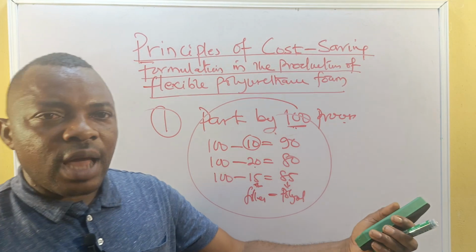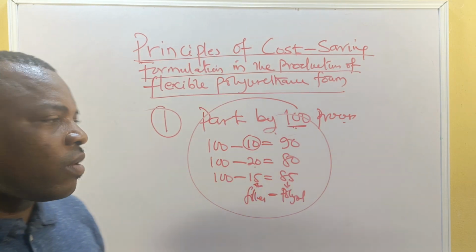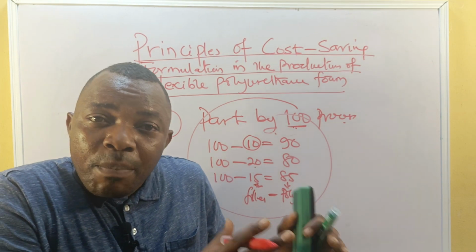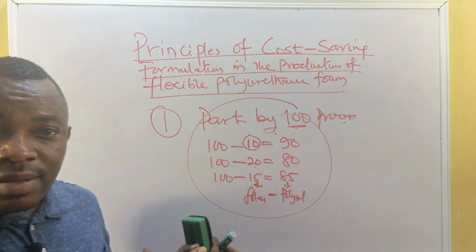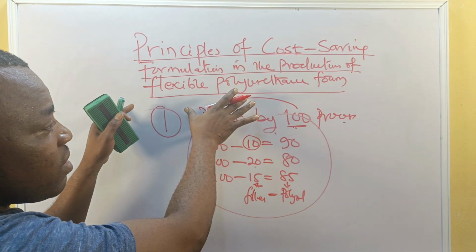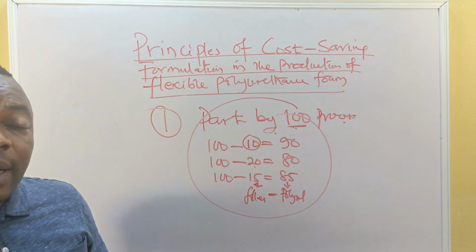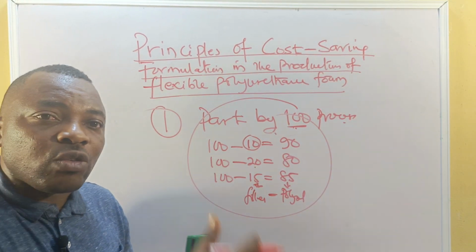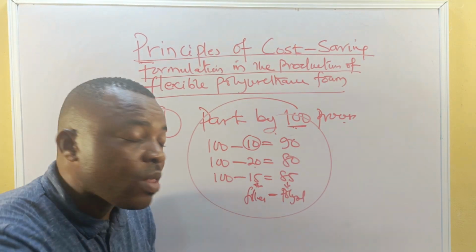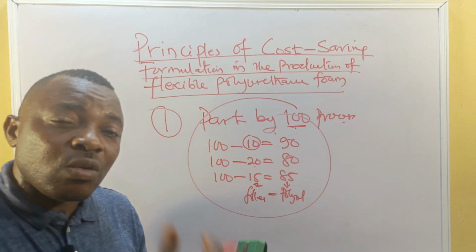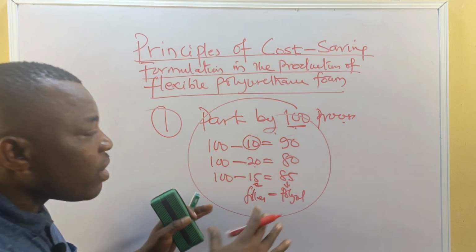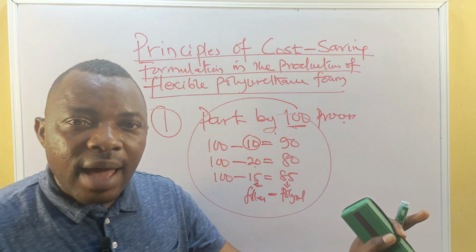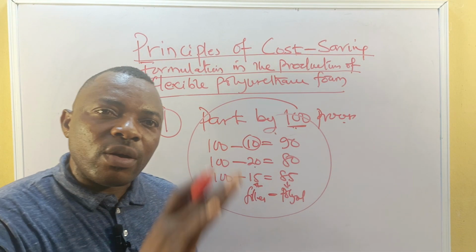Now, before you go into entire production, as a manufacturer that is using a continuous process, you must also put safety parameters or safety measures in place, okay, regarding your formulation techniques, in terms of choosing your TDI index that will enable you to meet up with that formulation. We are going to look at how to calculate this TDI index and design a formulation that is economical and also safe. Then we look at the calibration of all the dispenser equipment, such as all the chemical lines and your weighing balance, as well as your checklist.